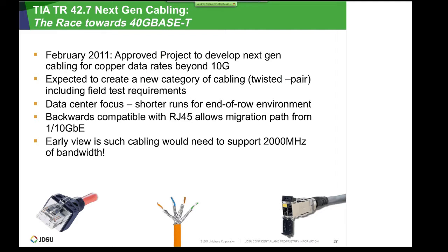If I have enough twisted, shielded and grounded pairs. Due to improvement of the quality of the copper cables, I'm speaking about category 6, category 7, the impact of the noise on the signal is much lower. That's why the level of the noise is also much lower. Due to that, signal noise ratio is very good. It was possible to reduce the output level of the signals.